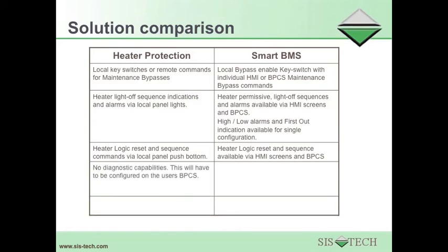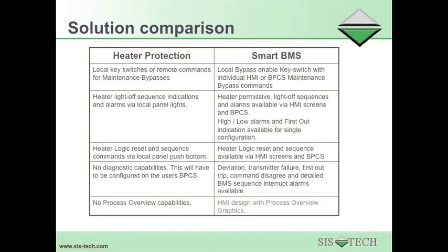The heater protection panel does not have diagnostic capabilities. The user will have to configure this on the BPCS. But instead, the smart BMS is designed to provide full diagnostics, including deviation alarm, transmitter failure, first-out trips, command disagree, detailed BMS sequence interrupt alarm, and process overview graphics.